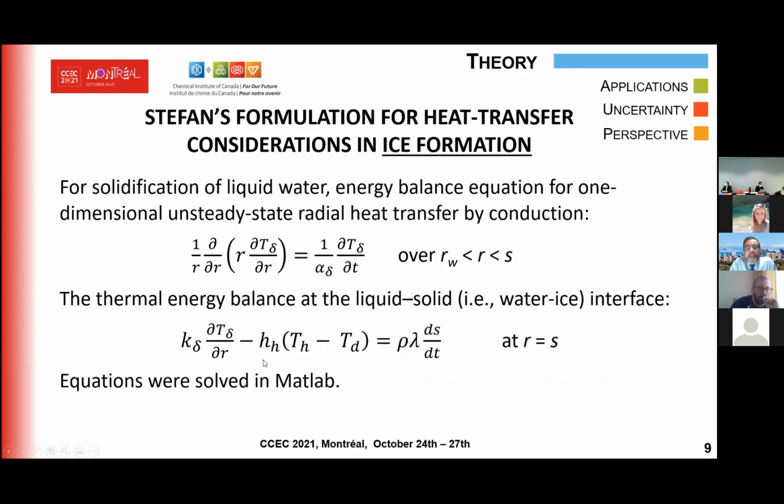Anyway, if you use this approach in cylindrical coordinates for the freezing of pure liquids such as water, these are the basic equations. There is an equation to describe heat flow in the solid phase, and there is a thermal energy balance at the interface.